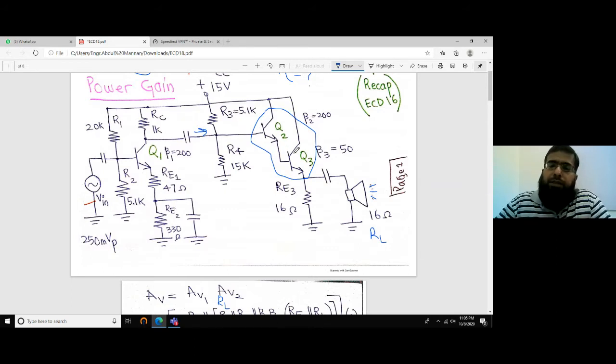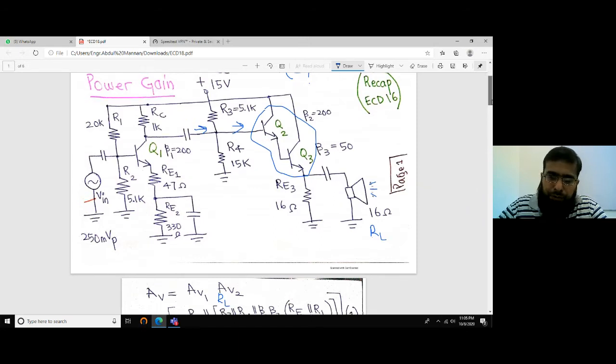And we studied in EDC that the junction resistances re2 and re3 are negligibly small when we see the input resistance from here. The resistance here is approximately equal to beta 2 times beta 3, the beta for this transistor and the beta for this transistor, times the parallel combination of these two resistors. So that is what we put here.